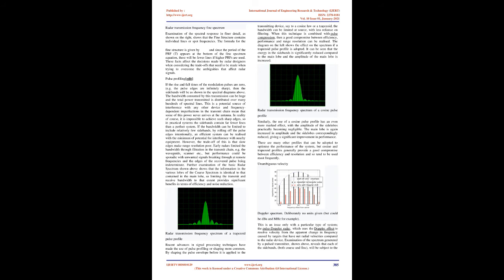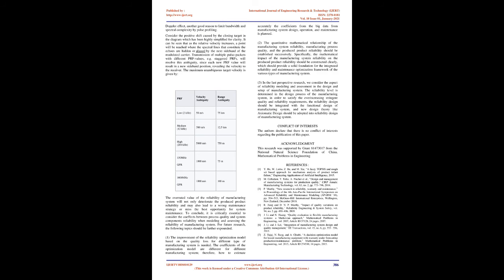3. Script waveforms with impairments configuration. This section allows generation of a sequence of pre-configured signals. The table contains multiple rows where each row defines a pulse signal with its required parameters and added impairments. When you click on the script assistant, a window will pop up, loaded with existent configuration.